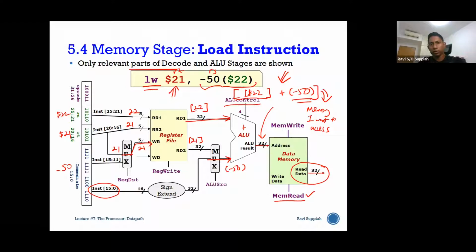First we talked about the instruction encoding, the register file, the decoding, the ALU, and now it's at the memory already. So I've generated the address that I'm interested in, I have sent that address to data memory, I've activated the memory read line, and then the correct data will now appear on the read data lines of the memory. Of course, you still need to use that to write back, but in a while we'll come to that.